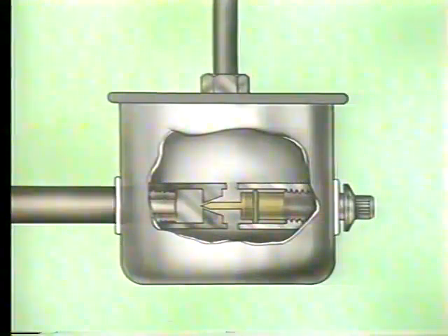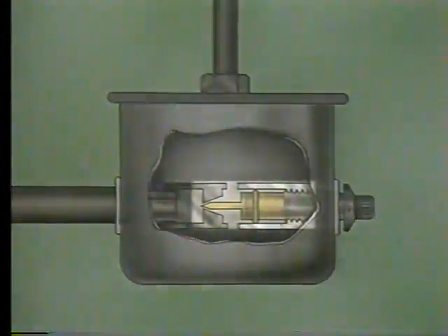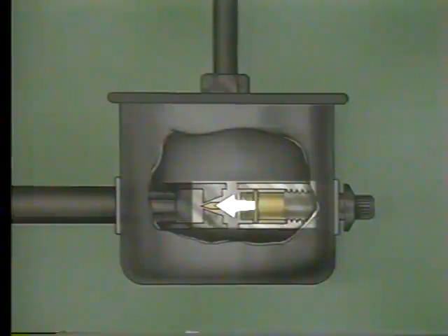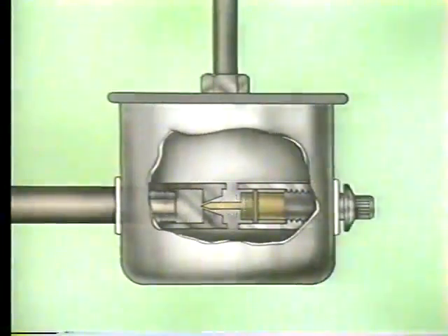As shown in this cutaway view, this volume chamber consists of an input port that receives pneumatic signals and a valve. The valve is comprised of a restriction and a needle with a threaded shaft. The size of the restriction is determined by how far the needle is inside the restriction. The needle is positioned by turning this dial, which is attached to the other end of the threaded shaft. The volume chamber also has a pressure-tight case and an output port.